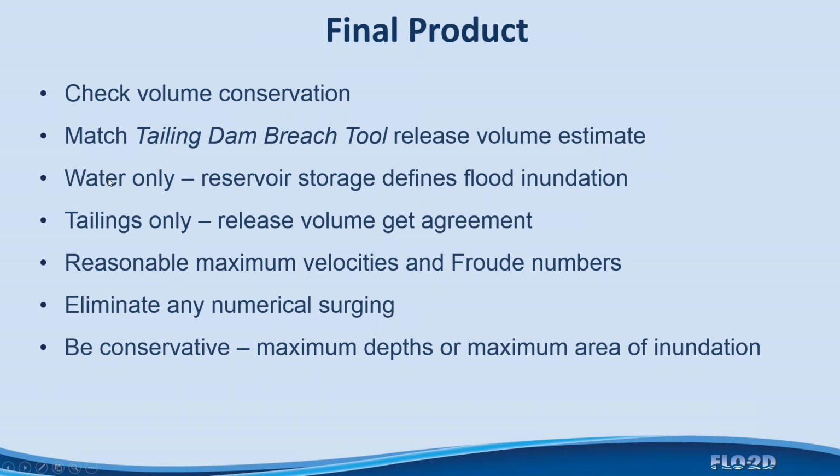Make sure that they match for the tailings breach material in terms of the volume. Do a water only, tailings only again. Make sure that you have reasonable maximum velocities even through the breach, and fluid numbers.